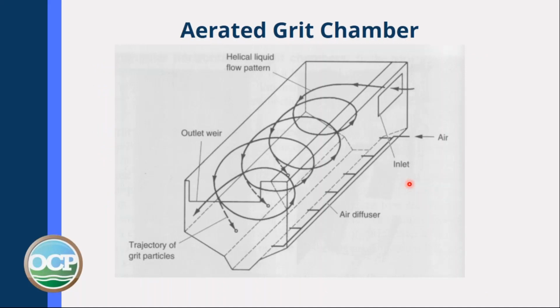An aerated grit chamber, again, here is your inflow of your material, and as you pump air through this, it forces the solution, the wastewater, to move in this direction in a helical way, and anything heavy will just settle out and everything light will be maintained in suspension and leave over this weir here at the end of the chamber.